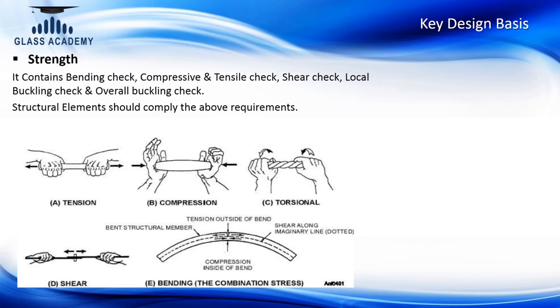And torsion is in many cases critical if the individual floor height of the building is like 4 meters or 3.5 meters and it has a large span of unsupported length, where torsion is critical. And shear, primarily checking for fixing connections and brackets. In many cases the curtain wall or glazing member is subjected to a combined action of tension, compression, and torsion, or it could be compression and torsion. So the designer should be able to understand clearly that action and where this check is critical.